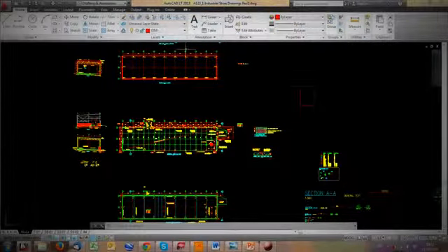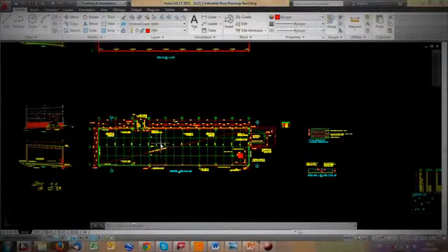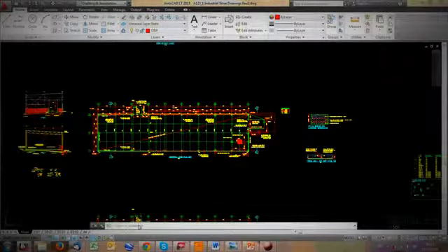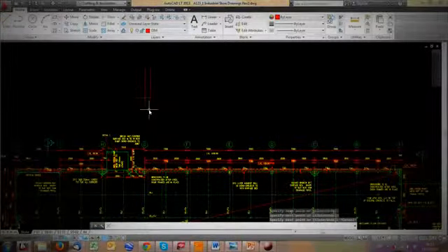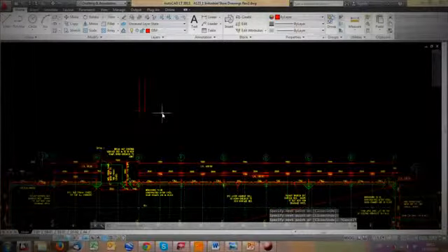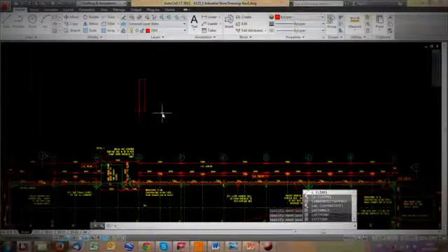Then, you can also use command lines, the way AutoCAD used to be used more, but it's still a very, very useful tool, and especially faster draftsmen like using the command bar, this sort of bar at the bottom here. If I want to draw a line, let's say, from the ribbon, I'll just click line and I'll draw it. Press escape to stop using it. But I can also start creating a line from my command prompt. I type L for line, and you can see at the side there are other things that come up.